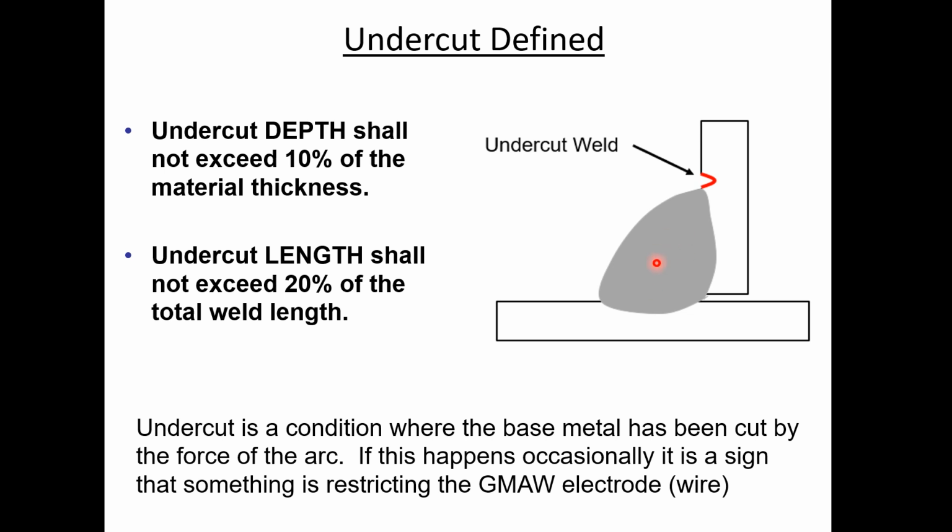So as soon as this weld goes into place, that's what it does, especially if it's been put in place well and it has good penetration. It takes all the heat that's inside and it's going to start dumping it out into all these different places. When it dumps it out, it actually creates a softer structure. We heat treat these areas known as the heat affected zone, right?